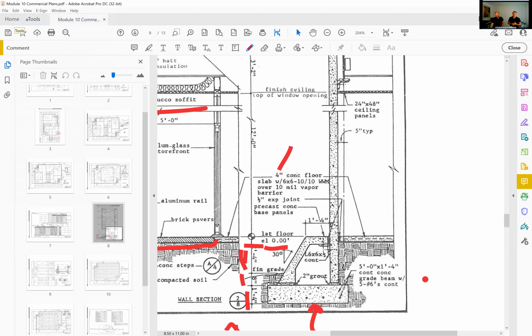Right, exactly. So let's say the test asks, how tall are the ceilings on the ground floor? It would depend on how they're wording the question, but we can look for our first floor elevation, and then look at the dimensions on the side. We have to think, from where to where are we looking?